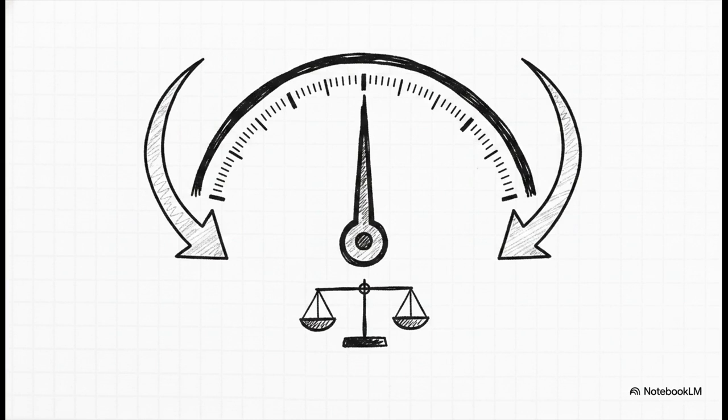So the crucial takeaway here is understanding how to actually read that signal. The 0 to 200 milliamp range represents the entire span of the speed bias adjustment. If you see a mid-range value, it simply tells the ECM to hold steady, no adjustment needed. But as that current swings out toward either extreme of that 200 milliamp span, it's commanding the ECM to dynamically increase or decrease the speed bias to match the shifting total demand.